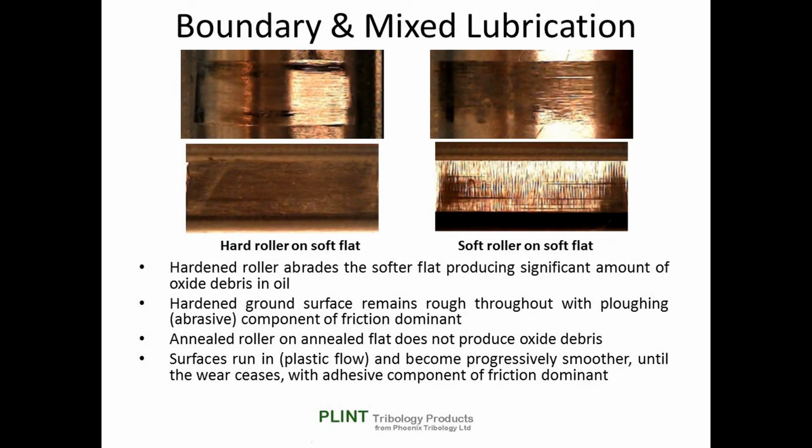A soft roller running on a soft flat does not appear to produce any oxide debris in the oil. The surfaces run in with a degree of plastic flow and become progressively smoother, with mean friction coefficient, instantaneous friction force, and contact resistance consistent with mixed lubrication. In this case, the adhesive component of friction is dominant.